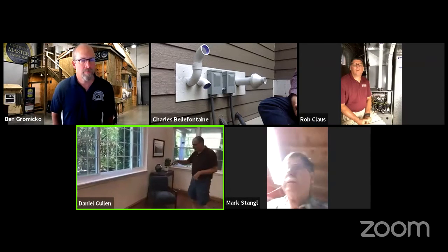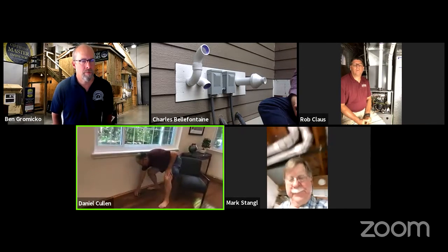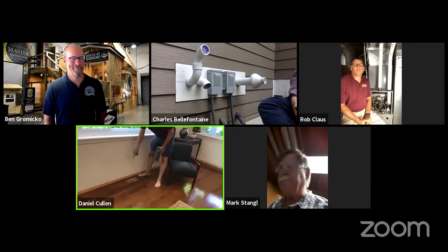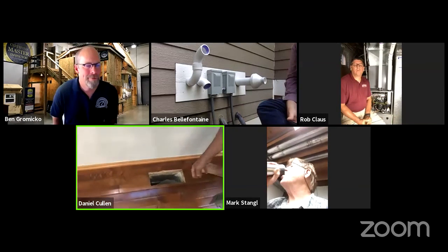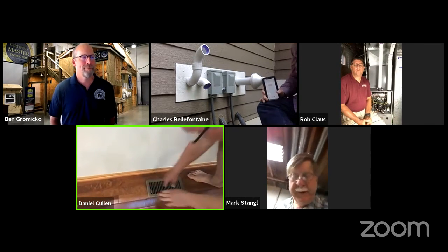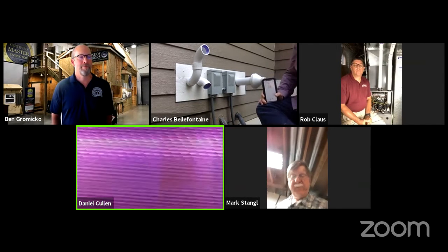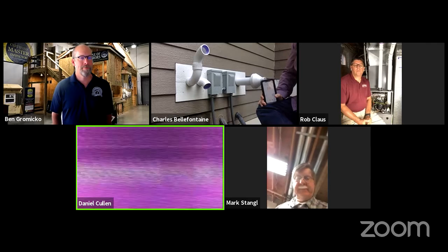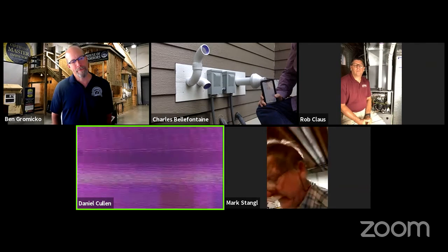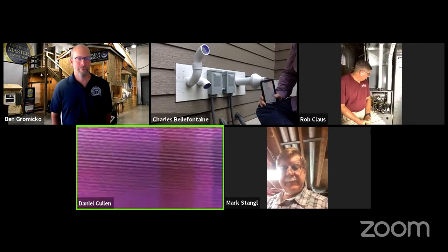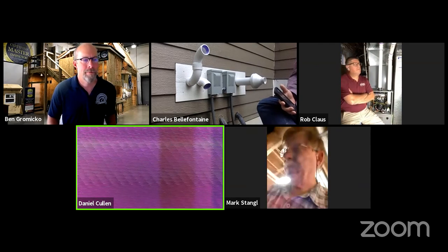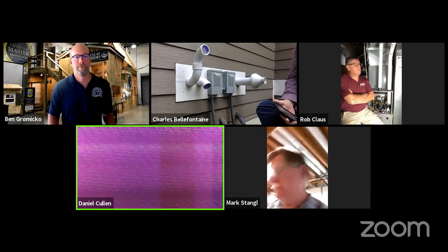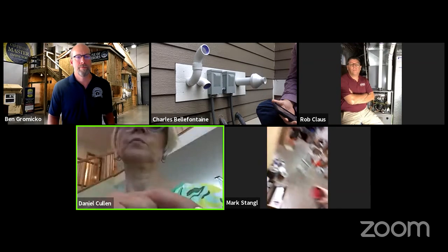So we have our ducts embedded in the concrete. And one thing I like to point out to my clients during the inspection is, are the register boots sealed, especially if we have ducts in the floor? So I like to go in, take a look, put my camera down in the duct itself. And as we all know, there's some dangerous things that can happen in under subfloor ducts, in ducts that are embedded in concrete. We can have asbestos ducts in there. We can have rotted out metal ducts in there, or quite often we can have PVC ducts that are much more impervious to